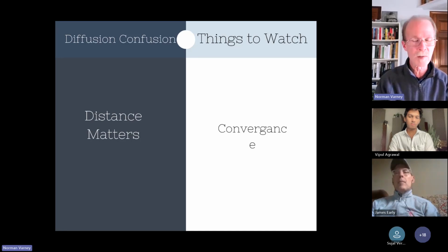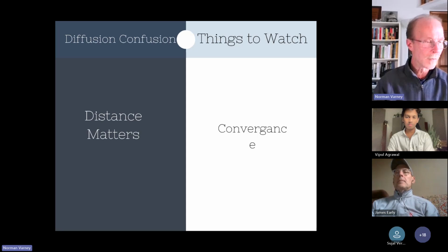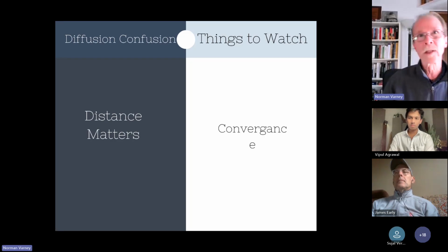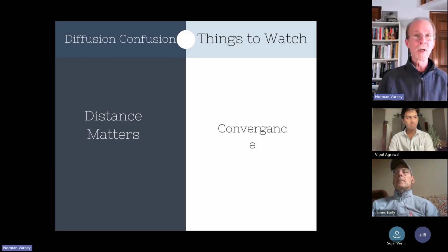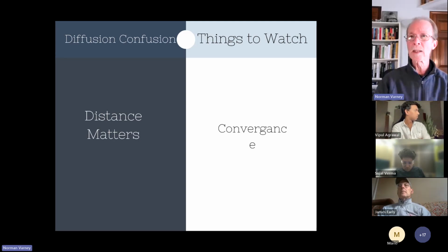And you say it's a small room. Well, a skyline type diffuser or number theory type diffuser has got to be effective down to say 500 hertz anyway, right? That's a lot of real estate, and so it's probably not going to work. But a polycylindrical or some other geometric type diffuser would work great there. So again, we've got a choice depending on the reverberation times of the existing condition. Do we want to absorb it, or if there's enough absorption in the room, then we can scatter it and get rid of that first order reflection point. Does that answer it?